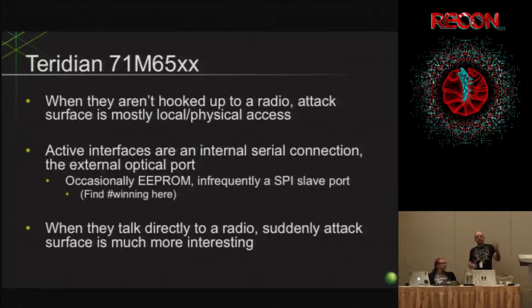There's the optical port on the outside. That's actually just serial communications, but it's happening over infrared. You have to buy a special infrared dongle to do that, but it's the exact same protocol. It's just half duplex instead of full.